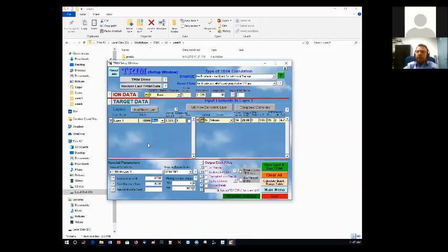Okay. Now, if you're with me, now we're almost there. There's one thing here. Decrease this total number of ions from this crazy number to, say, 100. Okay? Because otherwise it will send that many, 99,000 times those ions. Of course, that's going to be a much more reliable result because we won't have only a few ions, but we're going to be good for that.